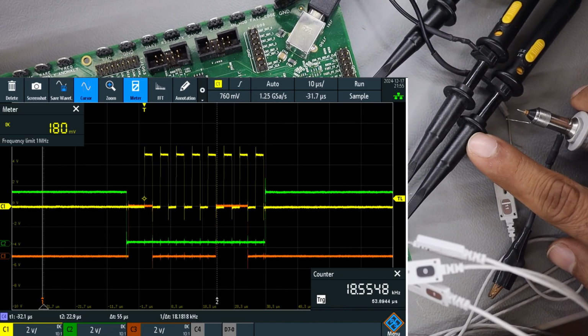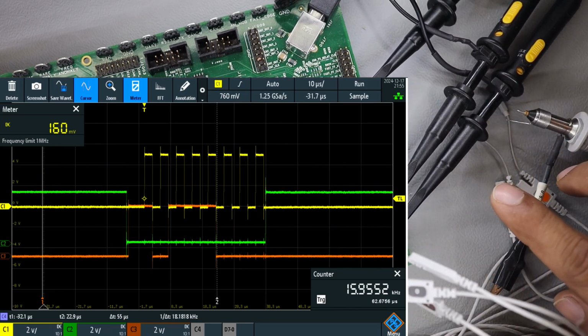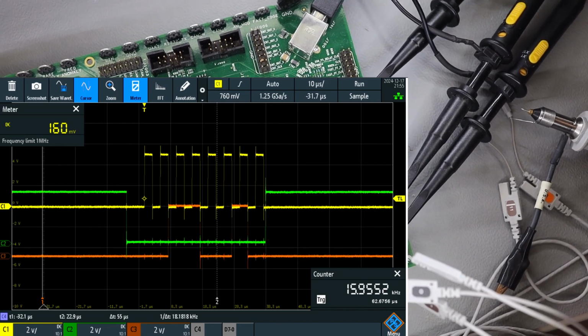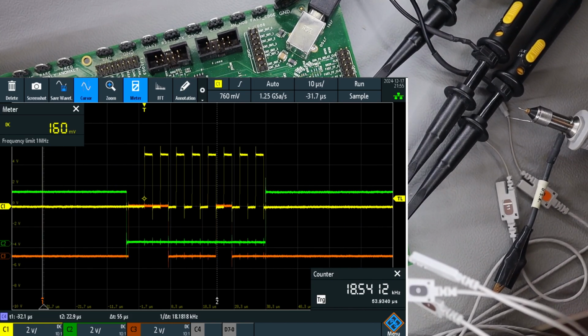You can see on your screen right now the web view of the RTB2004, and this is supposed to be the clock, and we see clock-like activity there. I'll show you some advanced triggering as well, how to stabilize a clock signal like that. You see this is flickering sometimes, and the reason is that our trigger is set to look for a rising edge, and sometimes it looks for a rising edge in the wrong place, so it's not able to find the appropriate trigger. We can easily fix that. Trigger should always be rock solid, so we'll try to find a solution there.